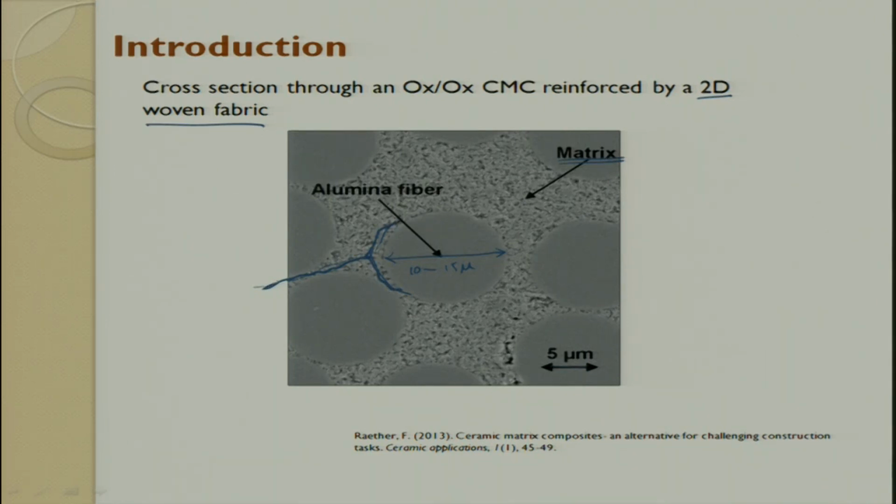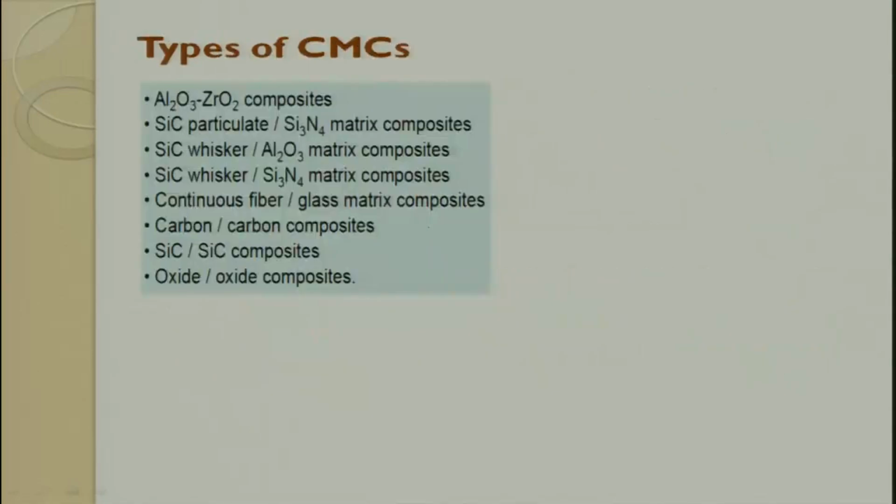The other way is, as the crack is growing, you try to pull this particulate out, or you try to pull this fiber out. When you try to pull the fiber out, the energy gets used in pulling it out because you have a very weak interface. Weak interface means it quickly goes around and tries to remove the particle very easily, and the energy is dissipated into the fiber in that location where the pullout has happened.